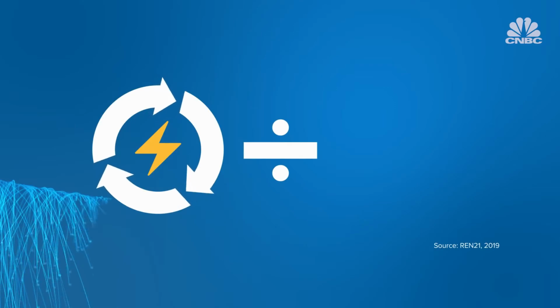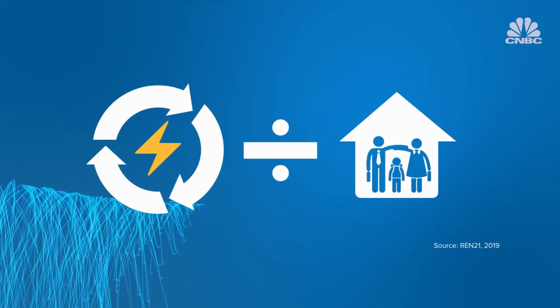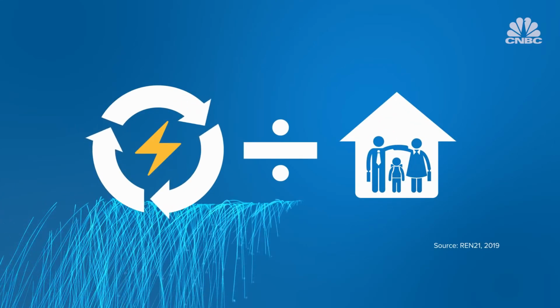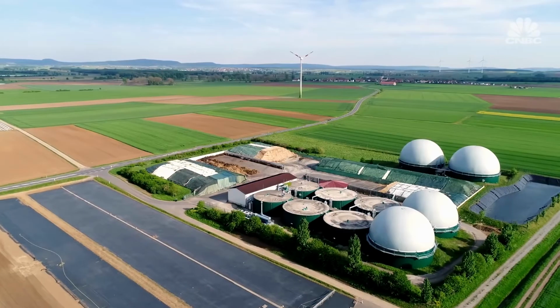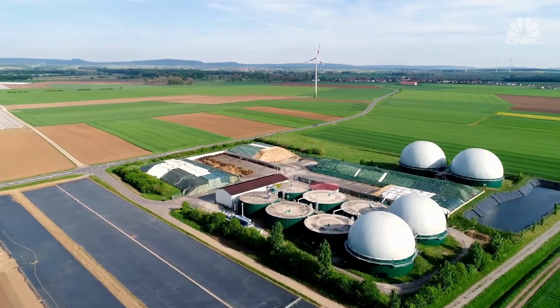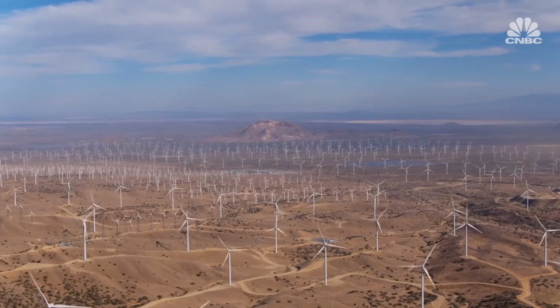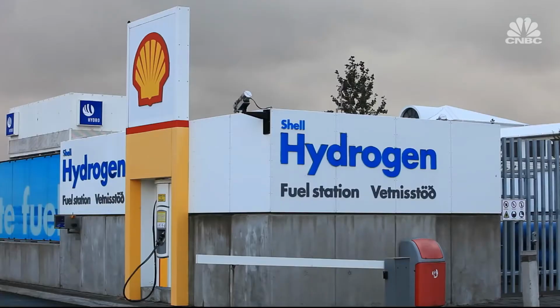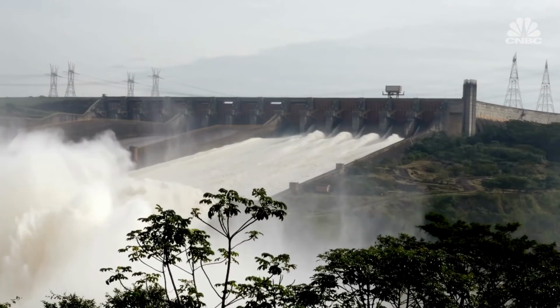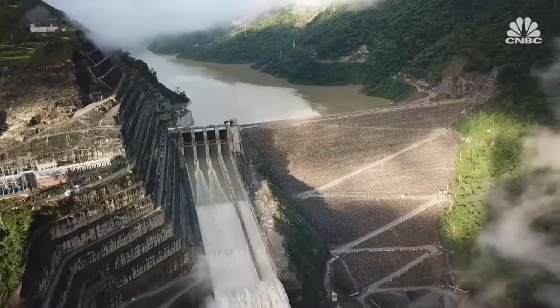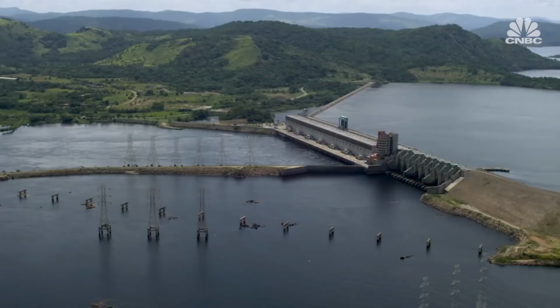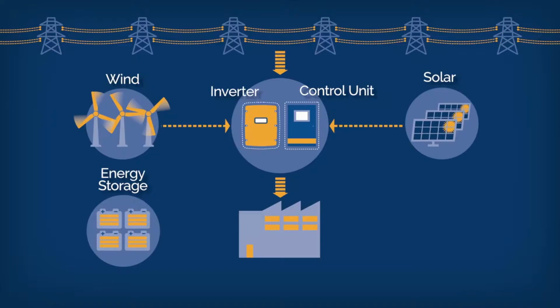Since the energy that most alternative sources produce is direct current, and most facilities and homes require alternating current, this results in a need for inverters. However, most inverters are designed not to operate when the grid is down. This function is for the safety of facility personnel. For the microgrid to continue operating, the inverter must be an island inverter, which is designed to operate on its own without being connected to the grid.